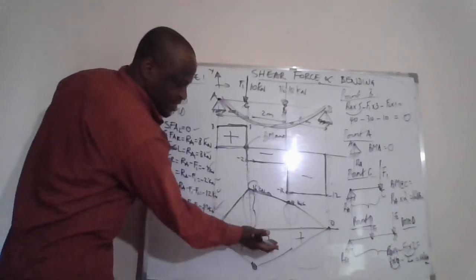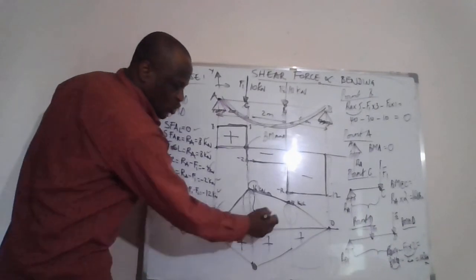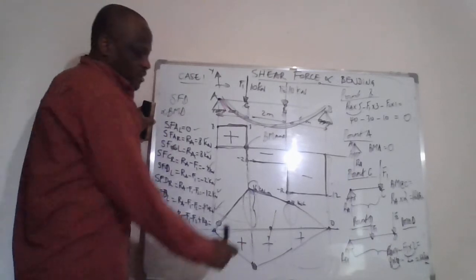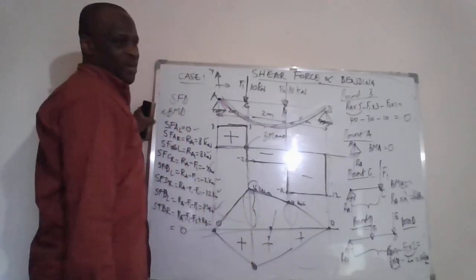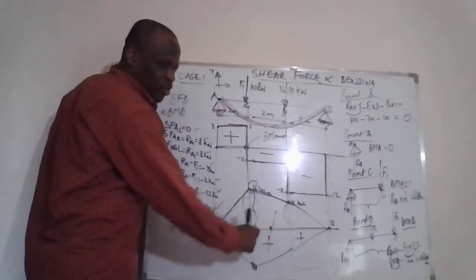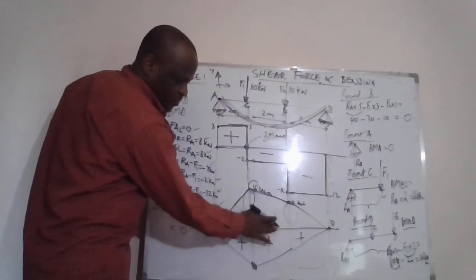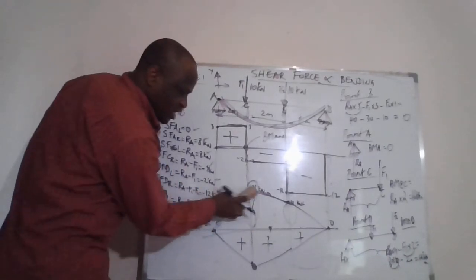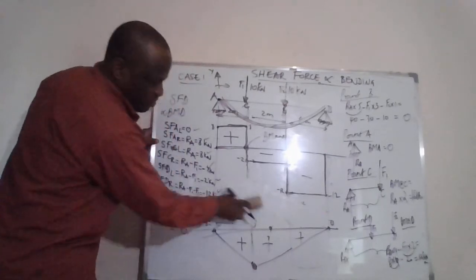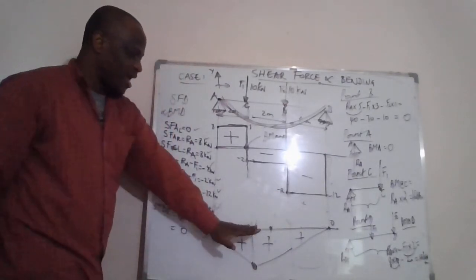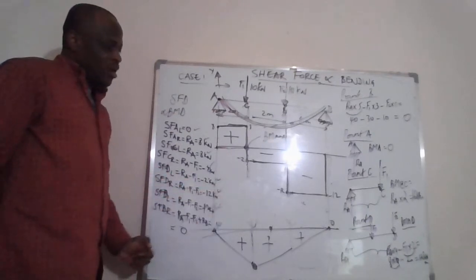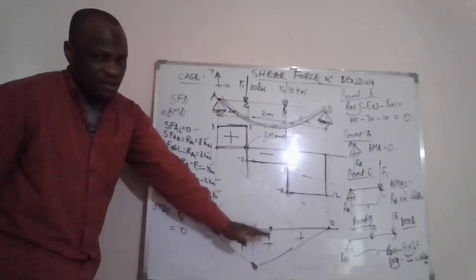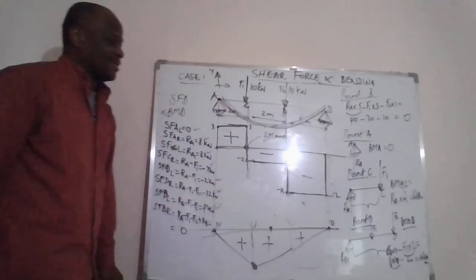And if in case the bending moment was crossing the 0 line, the point where there's a change from the positive to the negative value for the bending moment diagram is called the point of contraflexion. But in this case, we don't have a point of contraflexion because nothing is crossing the 0 line. And as I've said, we have a choice either to put it mathematically correct, by putting everything above the 0 line, or practically correct, by putting everything below the 0 line and putting the signs.